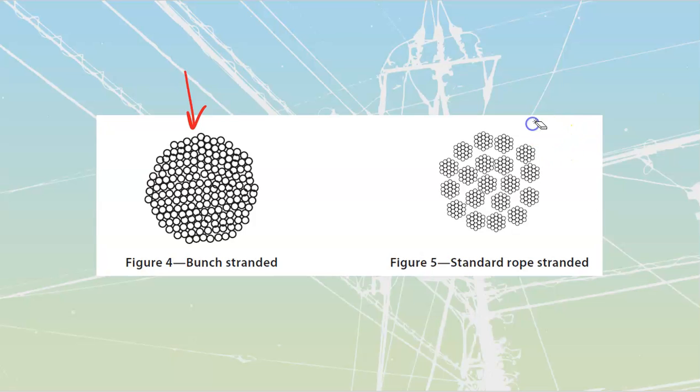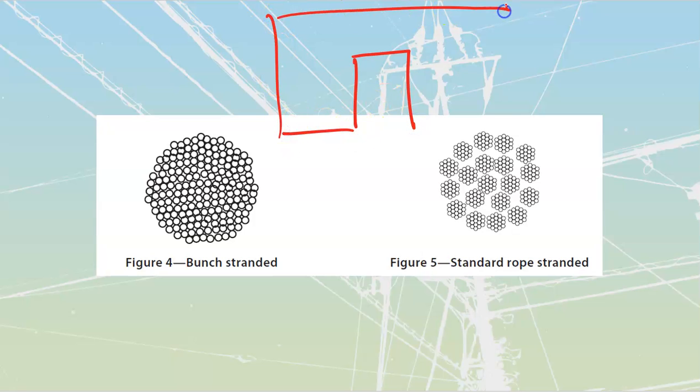Other ones that we do see that aren't listed inside of here are going to be flat braid cable. They talk about using it for battery grounding on a vehicle. We don't do that. We're electricians. What we use it for is bonding together of components. Where you will see it is inside of high voltage situations. Everything that is going to be metallic is going to have to be bonded down, including things like doors. And so you can't rely on the hinge because the hinge is full of grease.